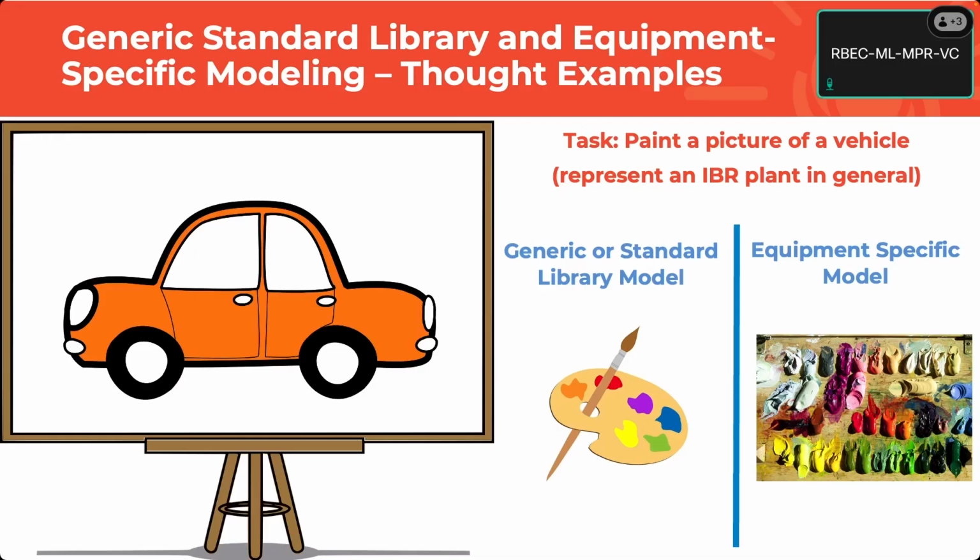So when you're trying to do these types of things, like representing a simple plant or representing a simple control mode, like for voltage control or primary frequency response, in most cases, say you simplified the ramp rates and gains on an equipment specific model, you can get a pretty good representation, right? And this here, specifically this example, is part of the reason why even NERC validated plants from mod 26 and 27 still were involved in all those events and still tripped offline.